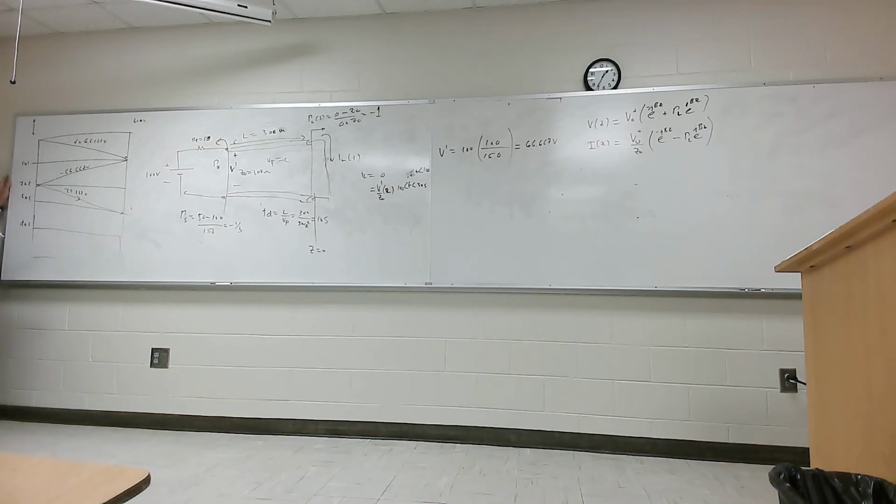Volts, right? Here, what's coming back? Minus 22.223. Then coming this way, what do we get? You would take that divided by 3 and get rid of the negative sign. What is that? It's going to be a small value, 7.4. Is it 7.4? 7.407. Okay, now that's the bounce diagram for the voltage.